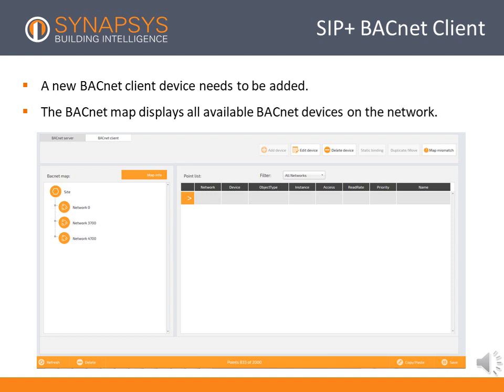In the bottom right corner of the page is a copy and paste button. This can be used to copy out all selected points in a CSV format. These can then be pasted into an Excel document to edit or create new points. Copy the whole table in Excel and paste back into the SIP+ using the paste feature.